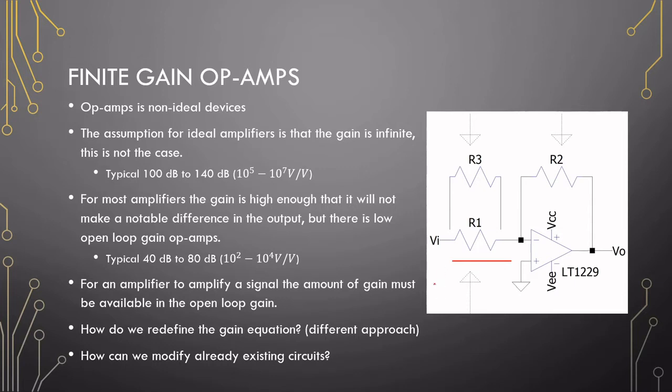But this is not a nice option for an inverting amplifier because you decrease your input impedance by doing that. Or you can go through the effort, desolder resistor 1 and put in a smaller resistor, again dropping the input impedance. Or lastly, by replacing R2 with a higher value. So those are the three options that you have in existing circuits.